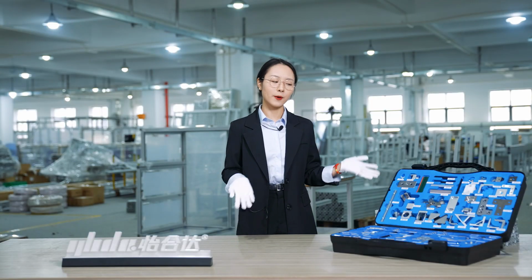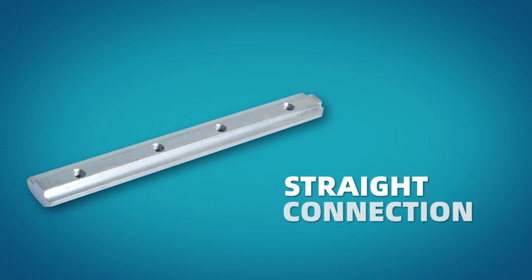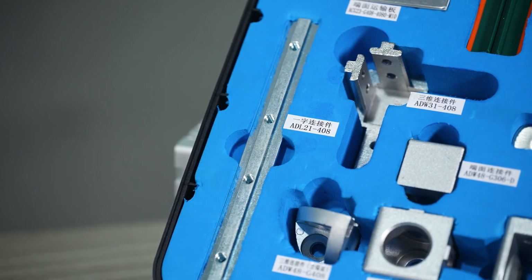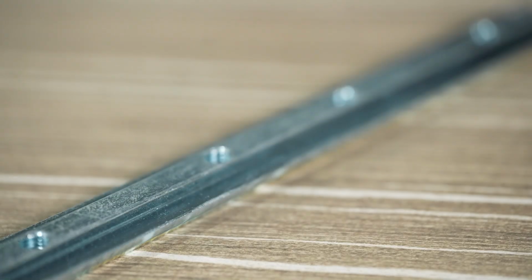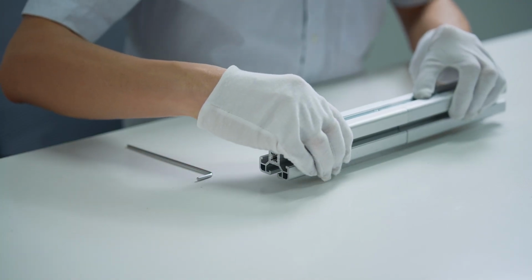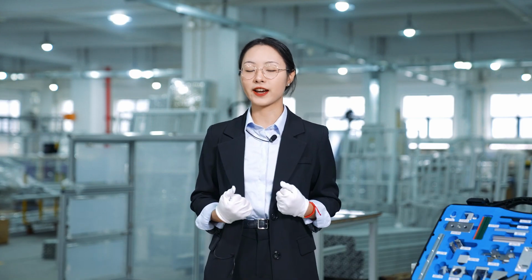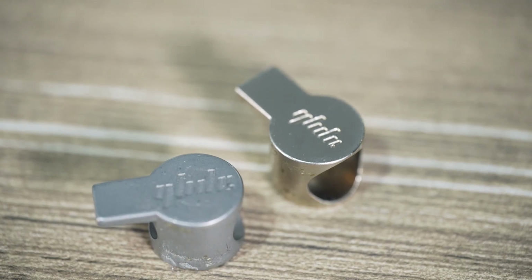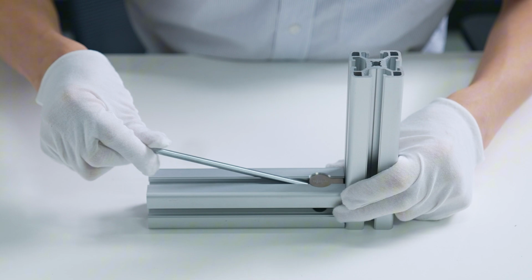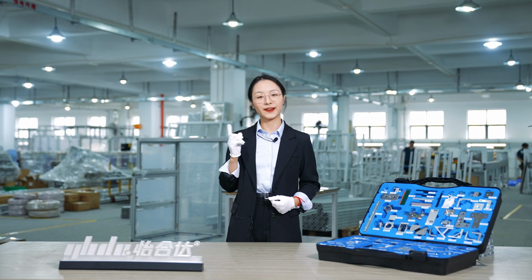Let me show you the most common connection methods for profiles. Straight connection, often used to connect two profiles. If the profiles are not long enough, a straight connector can be used for a high-stress connection. Built-in connectors, suitable for 90-degree angle connections, providing high connection stress, with a simple and aesthetically pleasing appearance. However, additional profile machining is required.